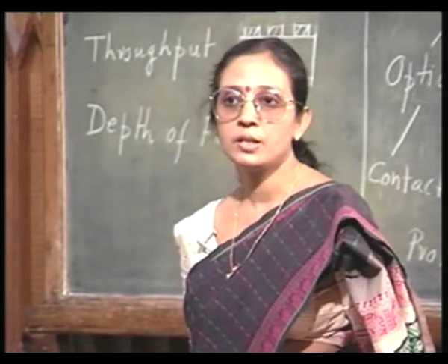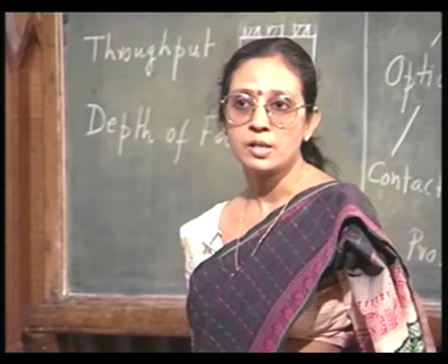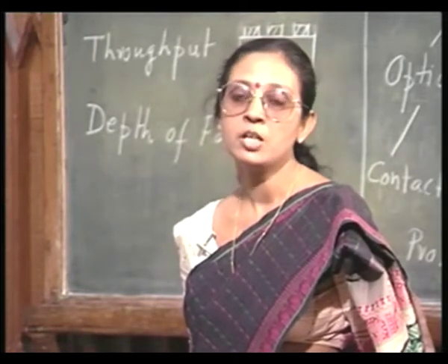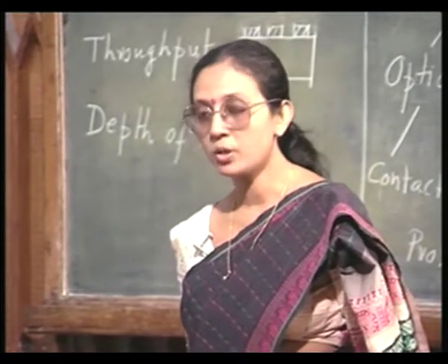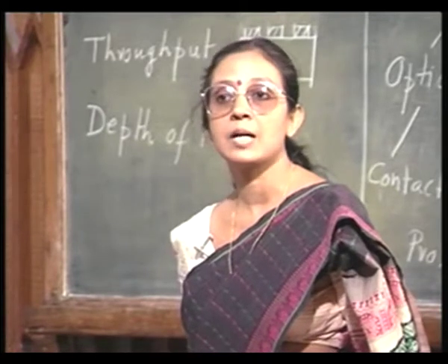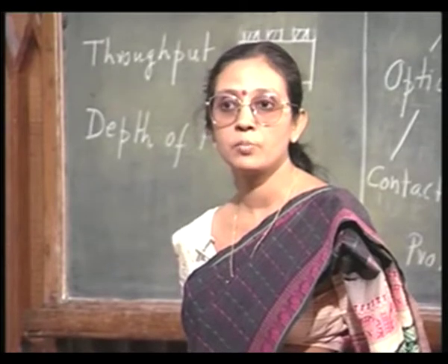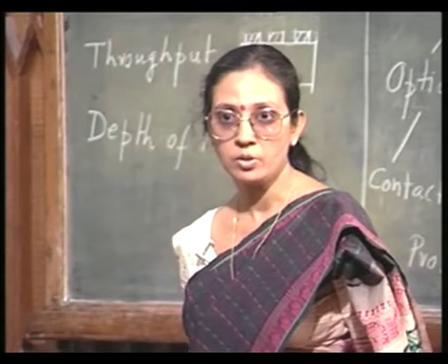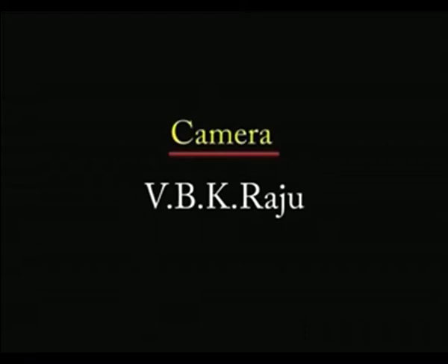However, optical lithography has the limitation of resolution, it is 1 micron or at best 0.5 micron if you go to deep UV. Suppose I want to have a really sub-micron technology, then I may have to employ other means, and that brings us to the E-beam lithography, which we will be discussing in the next class.